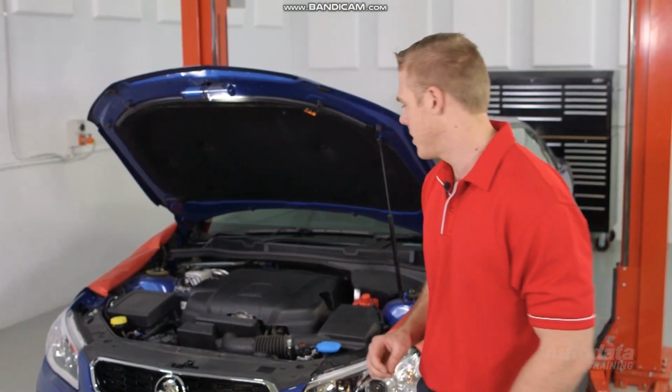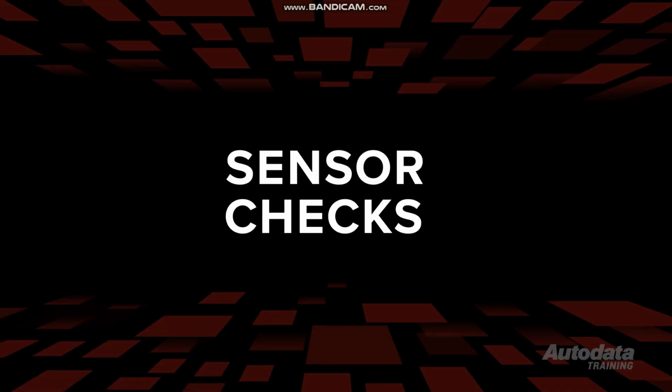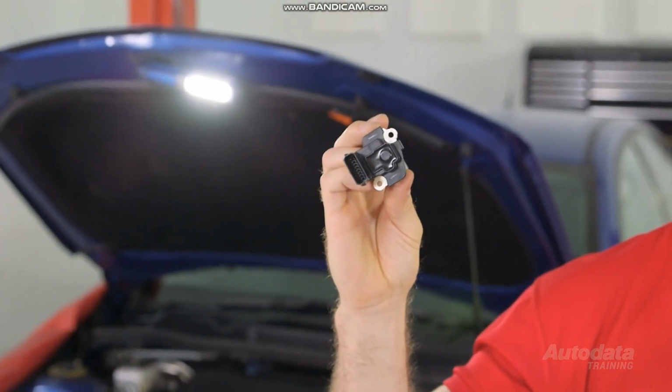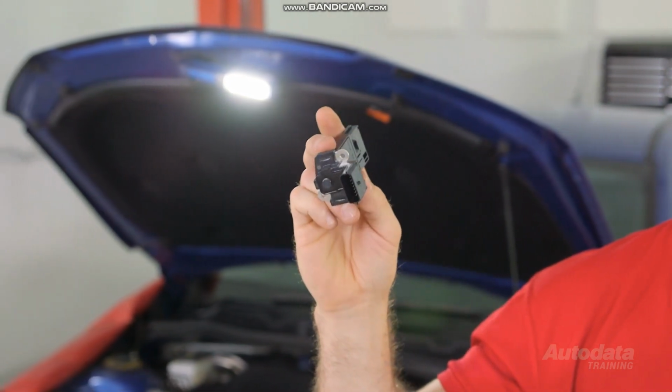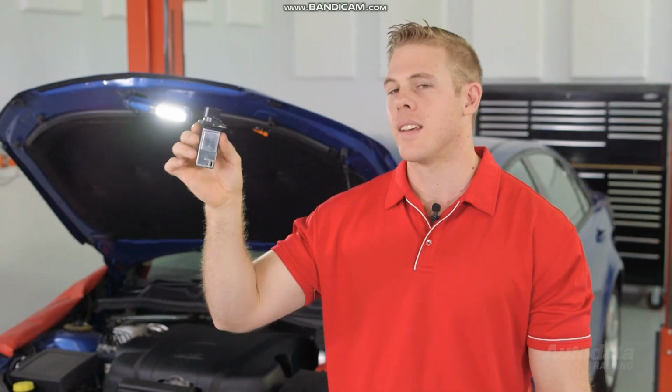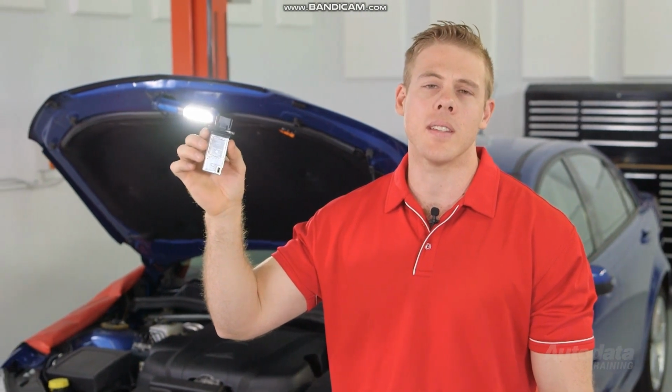Let's go through the steps needed to successfully diagnose a barometric pressure circuit fault. We may need to remove the sensor and inspect for contaminants or blockages. Ensure the sensor isn't damaged in any way. If this is okay, we can now test the integrity of the circuit and sensor.